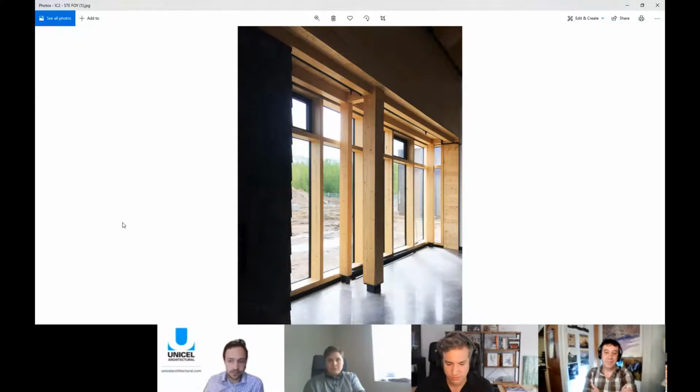The main aspects of the timber curtain wall is, first, of course, you've got the look and feel and warmth of the timber as opposed to conventional aluminum. That timber curtain wall is also really, really energy performant. So this is a system that, when combined with the proper glazing, is passive house certified. And thermal performance is really important in terms of timber curtain wall, because you want to avoid any kind of condensation. You want to protect the wood, so that's why you need that thermal performance.